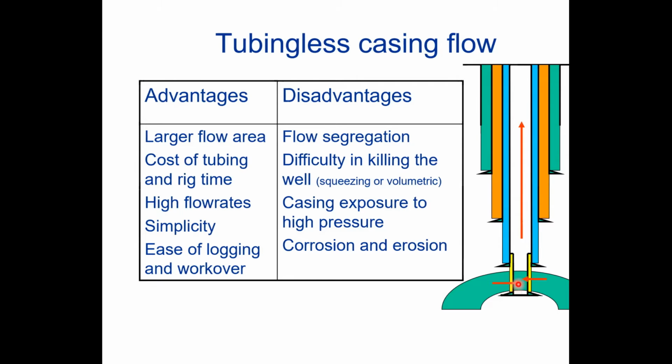Because there are three elements in pressure drop to surface. One is hydrostatic head, because you have the fluid here and that fluid has density, therefore there is hydrostatic head. One is friction. Friction pressure drop depends on velocity.